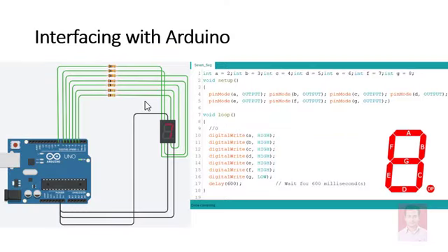this is a code that is going to explain the interfacing of this 7 segment display with Arduino Uno. I'm using Tinkercad for this design. So what is done here, all pins are connected like this. Pin number 1 is going through like this. It is connected to different pins of your Arduino Uno. Instead of using pin number 1 to pin number 10, I'm using A, B, C, D characters as my reference. So A is connected to pin number 2 of Arduino, B is connected to pin number 3 of Arduino, C is connected to pin number 4, D to 5, E to 6, F to 7, G to 8.